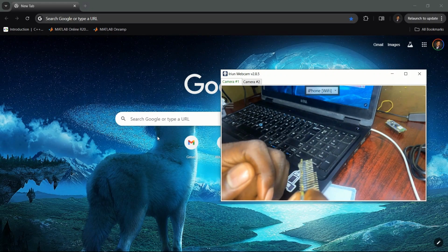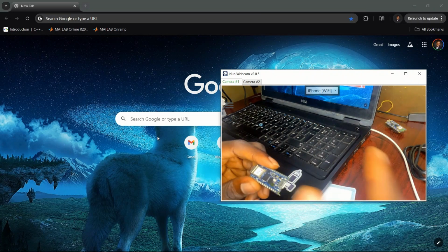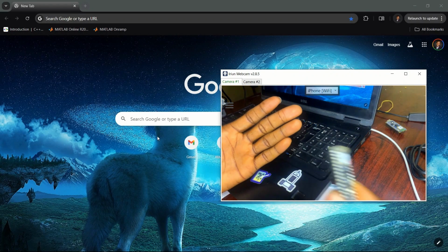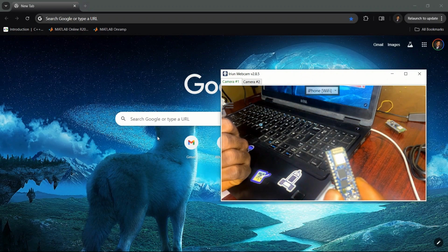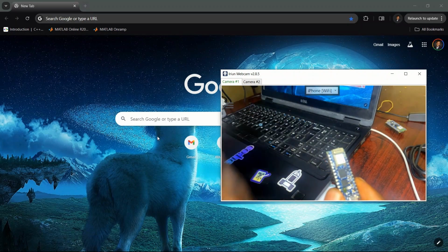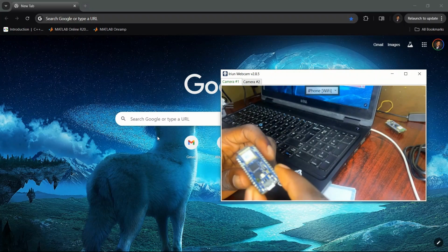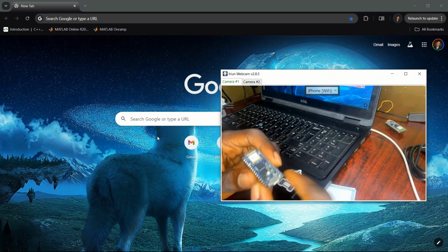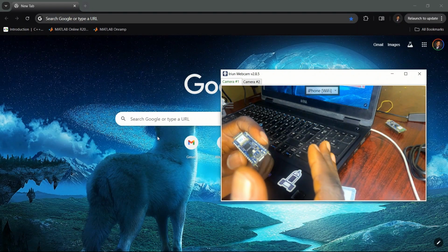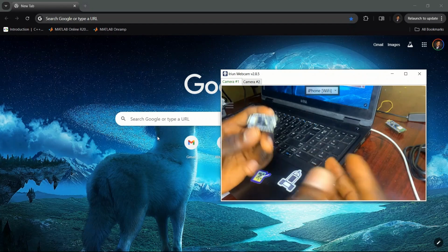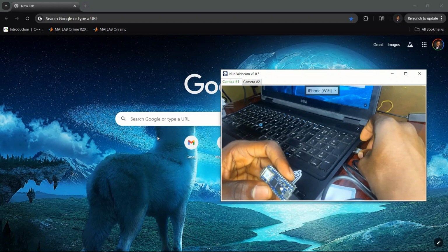The way this works is that on a normal day, if you connect the Arduino Nano RP2040 Lite to your computer, you're not expected to see anything, like a mass storage device being plugged in. You can only notice that something has been plugged in when you try to connect the ports using the Arduino software. But in this case, whenever you plug in the Arduino RP2040 Connect, it shows as a device connected to your laptop, as if you plugged in an external hard disk or a mobile phone. So I'll just go ahead and connect this to my computer.